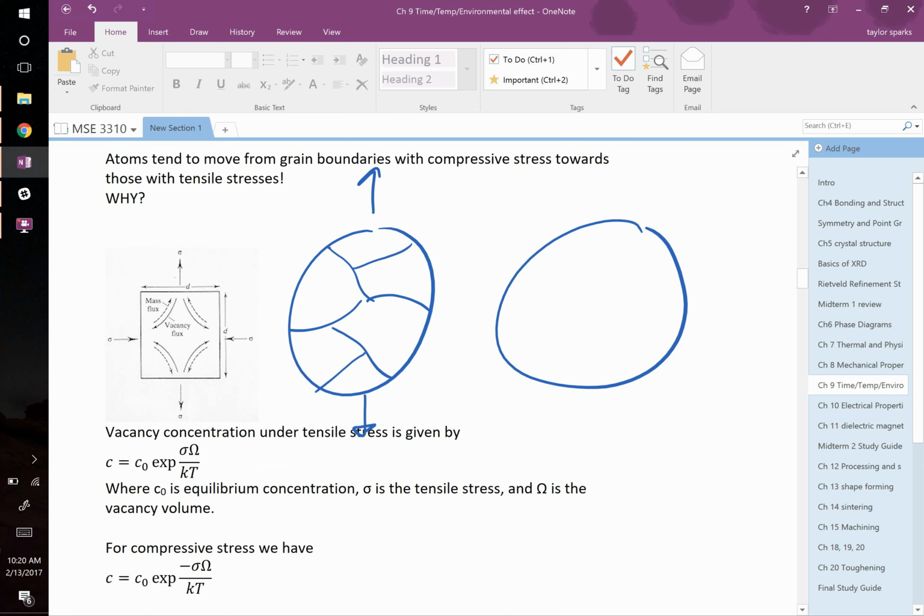Well, the load's not changing direction. Mass is flowing here and it's flowing here though. So what will these grains start to look like? What's that, Gabe? Yeah, they're going to start to stretch out. You're going to get things that look kind of like, how do I draw this? I haven't tried to draw this before. Kind of like that maybe. They're stretching more vertically, because it's going to squish in from the sides, it's going to grow vertically.